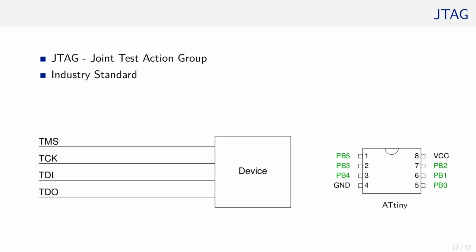For instance, the ATtiny has 6 pins available for data transfer. That pin count includes the reset pin, and some of the pins might be already used to communicate with periphery. Disconnecting the periphery to make room to attach a debugger is exactly what we wanted to prevent, since we would like to test the MCU in its habitat.